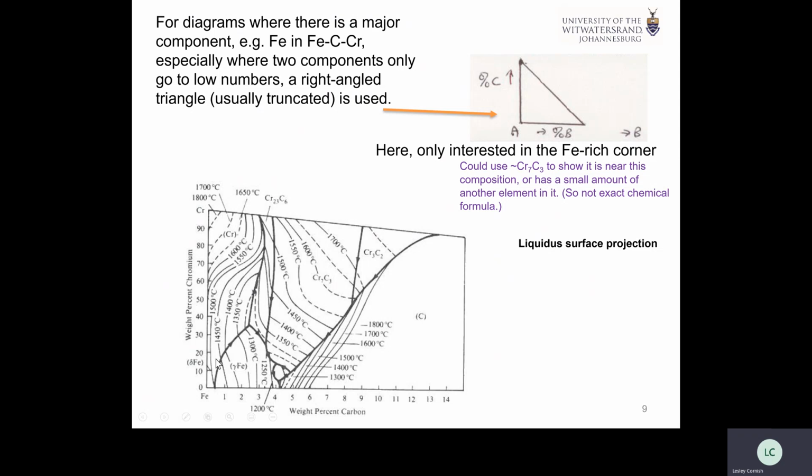So here it's going to solidify to the chromium-rich solid solution, and a little bit of jiggery pokery over there because iron and carbon dissolve in each other, and that's an isomorphous phase diagram across there. So it magically swaps from chromium to delta ferrite over there, but it's basically the same phase, body-centered cubic. It's just that number of atoms is changing, the proportions are changing. Then anything over here will solidify to austenite or gamma iron.